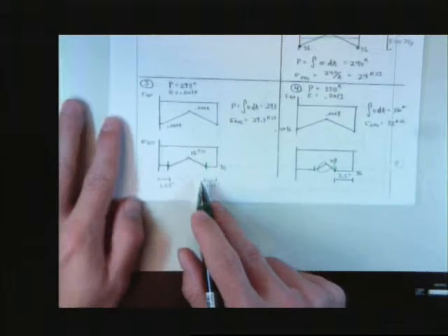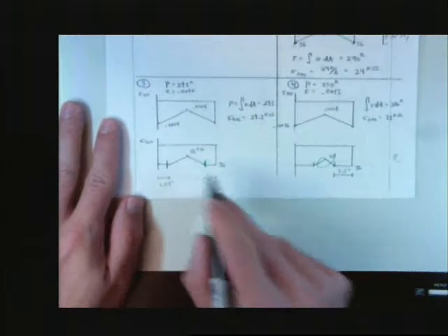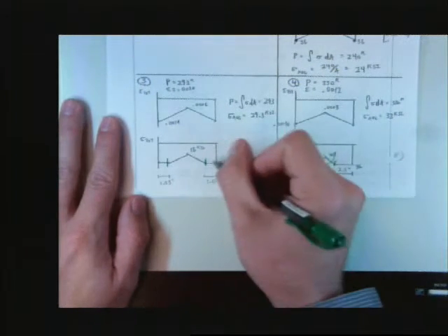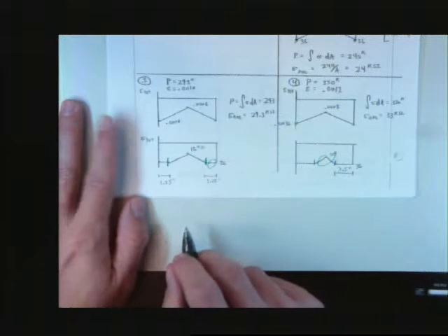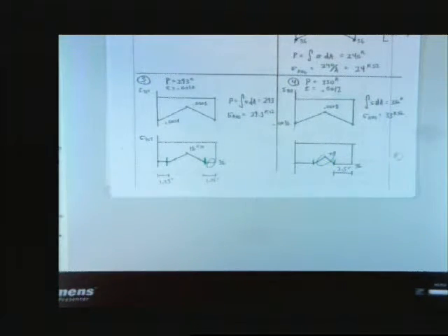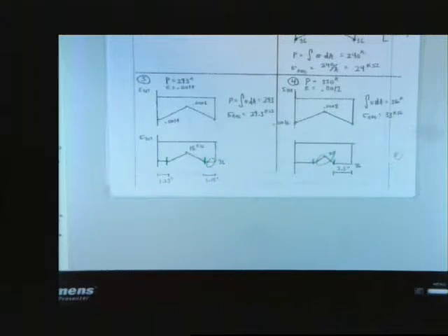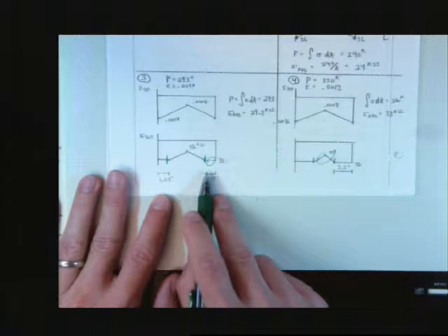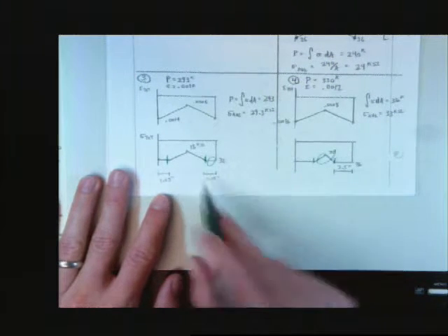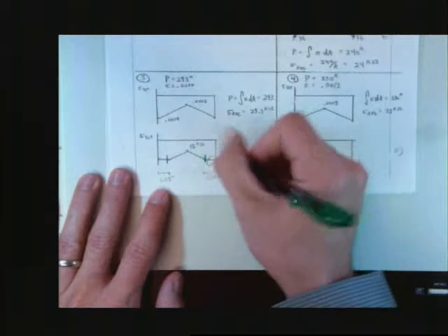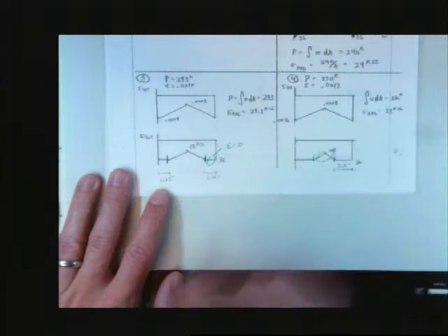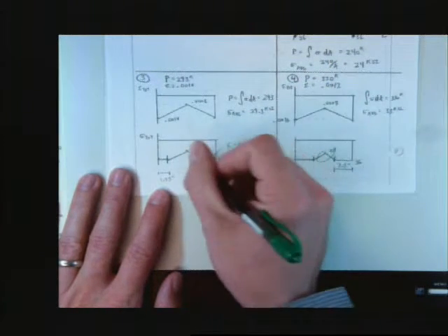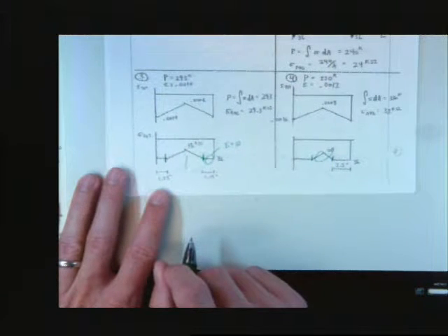Anyway, when we get to this point where this material has lost its stiffness, it's like it's not even there. It's like the area is gone. Does that make sense? But we don't do that. The area didn't leave. So what we do instead is act like the modulus in that area, the E in this area, is 0. What's the E in this area? 29,000 KSI.